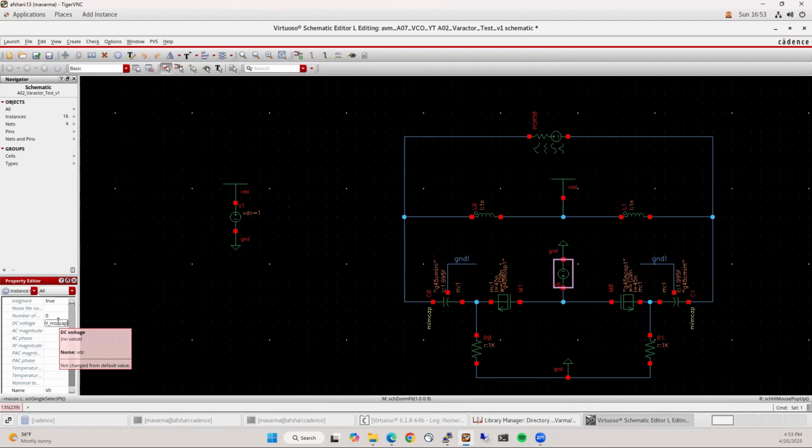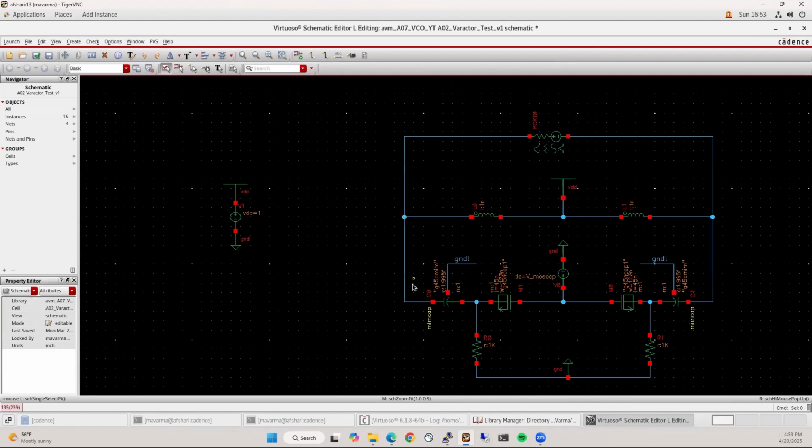MOS cap, right? Okay, so since this line is at 1 volt right now, then I have to bias this higher than 1 volt, right? And that body is probably going to be connected to 1 volt, which is not a good thing. So you want to keep this at ground, DC, and that's why we have these big resistors. Since these resistors obviously don't draw any DC current because both sides they are caps, it would bias this node at DC, and it's large enough that for AC it looks like an open circuit. And that's basically the idea.